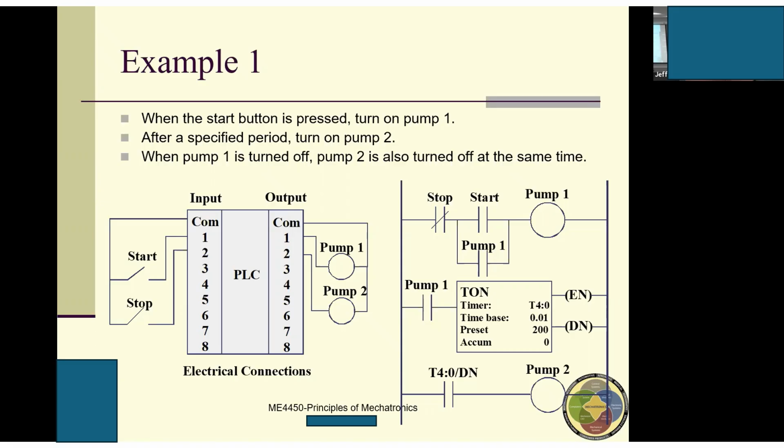Start, stop, seal. Yes, okay. As I said, if you want to build any automation, always put this one as your first rung. So, start, stop, seal-in circuit.